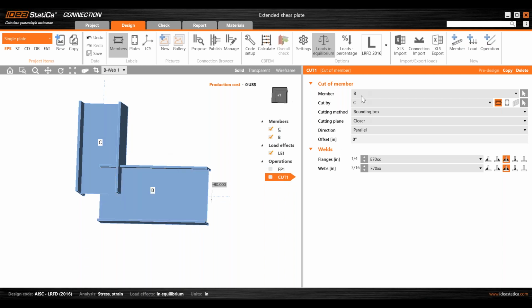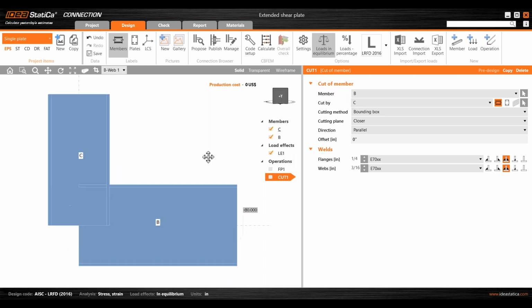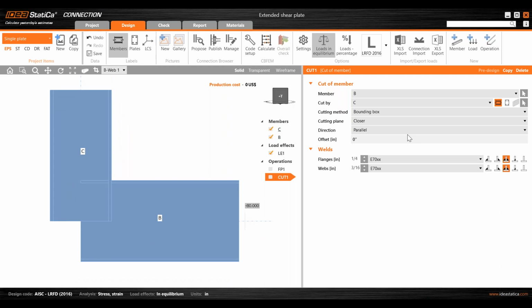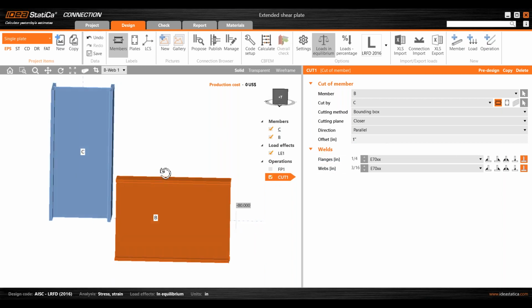And a lot of the cuts, I know it's adding on, say if you need to leave a 1/2 inch gap. So obviously in this cut of member, there is an offset. So you can say what that dimension is for the offset itself. And then you just have to turn off the weld so you can leave that gap. I'm not sure if that 100% answers your question.